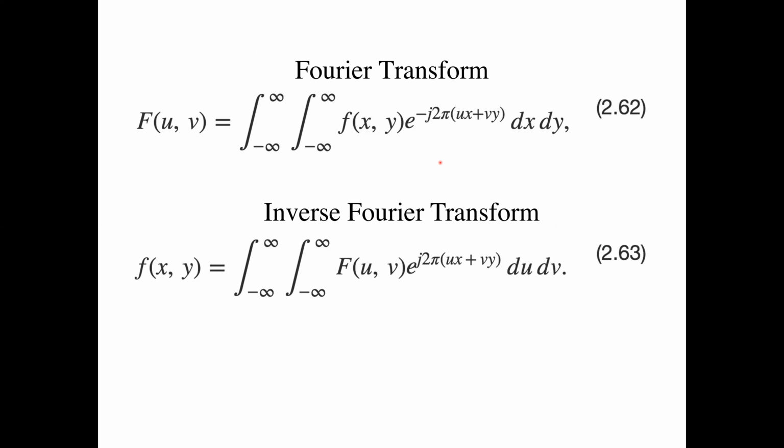If I have a function that looks like, say, a triangle, it's an amplitude that goes up and it stops and it goes down and back to zero like that. And ask, what frequencies are in that function? There is no single frequency, single sine wave that makes that function. You need to compose a set of sine waves together with different coefficients to make that triangle, right? And so the Fourier transform is the transform you take to figure out what that composition looks like. Okay? And we'll take a look at an example.